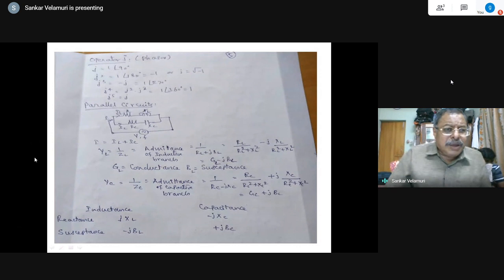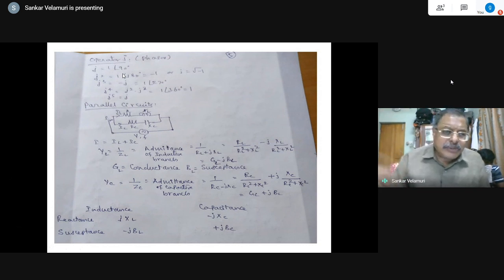Now, just briefly, I have written here to make you understand that we have to use the phasor notation. j is not a simple quantity here. In the mathematical sense, it is equivalent to i equal to square root of minus 1, and at a later stage we will talk about residues in mathematics also, the same quantities. But in alternating current circuits, we use the notation j as a phasor, which when applied to a vector implies that the vector with the same magnitude rotates in the anticlockwise direction by 90 degrees.